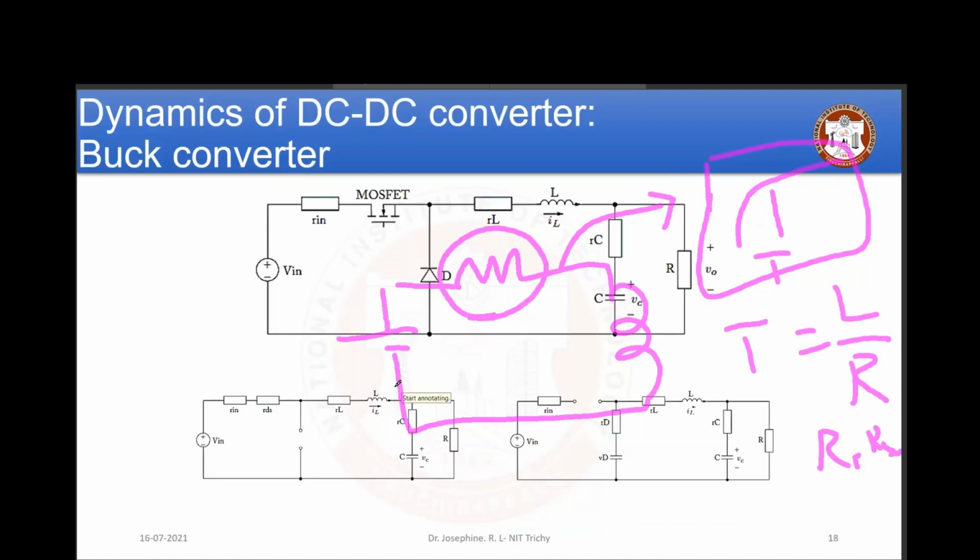So you have to consider that. Once you find this, you will get a relation between L and RSC. By taking these 2-3 instances, you can find the L value and RSC value. You can use a DSO in your labs itself to find the time constant, I mean the L value and R value. You don't need an LCR or Q meter.